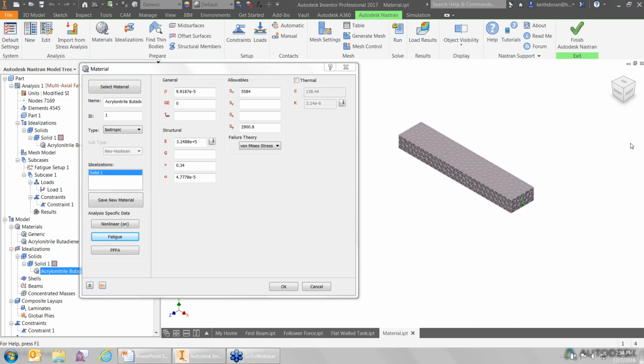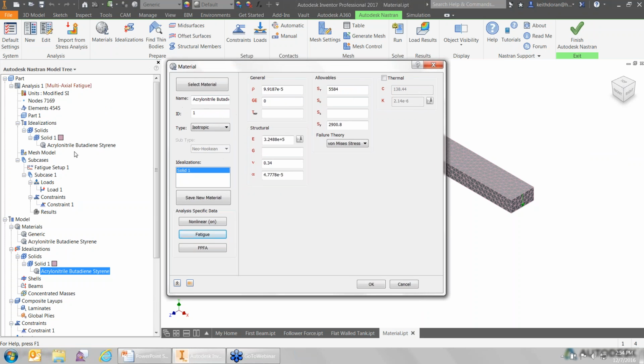I've only used linear static simulation in Inventor, where you need to input the number of iterations and check convergence before you determine the validity of the study. I noticed that some of the steps in the nonlinear analysis were iterating 20 to 30 times. Does the step simply not end until you reach some predetermined convergence data? Yes, so Nastran is doing some of that work on its own in the background. There are some additional configuration settings